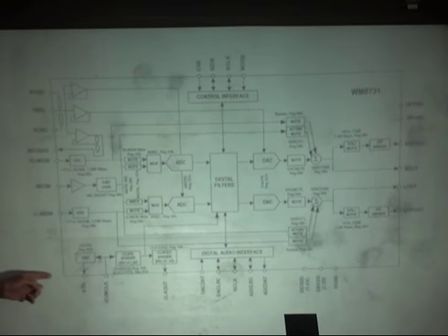So when you reset the board, when you turn on the power, there's going to be a dialogue between the FPGA and the Wolfson chip to determine left channel gain, right channel gain, left channel mute, right channel mute, a whole bunch of parameters, 10 or 20 parameters.